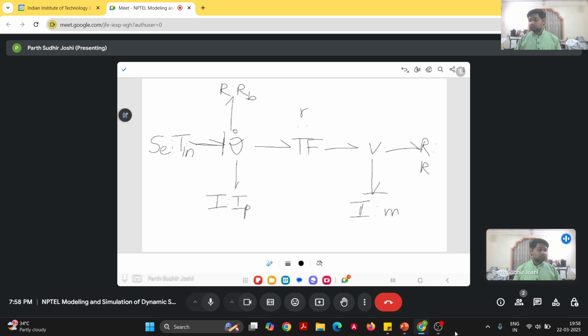And for the transformer, here we have a one junction here as well as here. So we will have the causality for the transformer element like this, like this. And then the causality for the other two elements, we will show it like this. And finally the causality for the resistance element, we will be representing it like this. So this completes the bond graph for this particular system.